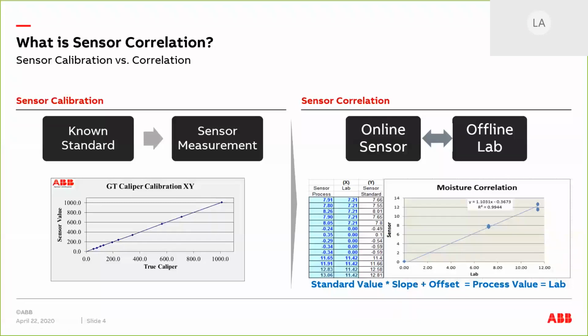We're only calibrating that sensor. And once the sensor is calibrated, we use a set of external static check samples to verify the stability and the repeatability of the gauge. Typically you see your QCS maintenance service provider to perform monthly check samples. So here we're only testing the stability and the repeatability.